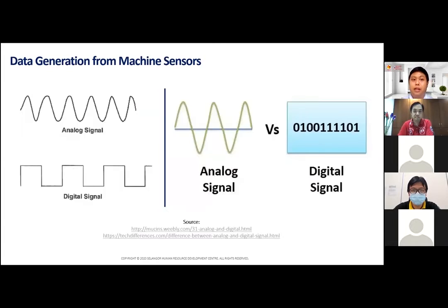Now, data communication from machines is not something that is magical, right? Basically, machines speak to each other in a common language, right? So from the very, very basic level, it is basically raw signals coming from machines, right? Coming from your sensors. It can either be analog, which is basically variation in measurements. So analog signals come from, like, temperature, humidity, distance measurements. So those are all analog signals. Digital signals are basically ones or zeros. Ones or zeros means it's either on or off, right?